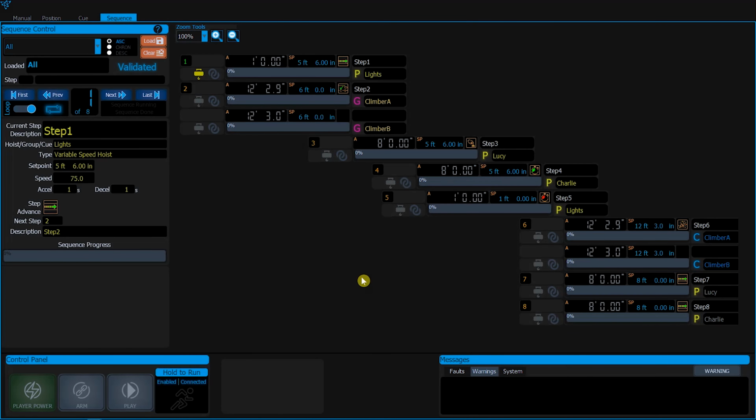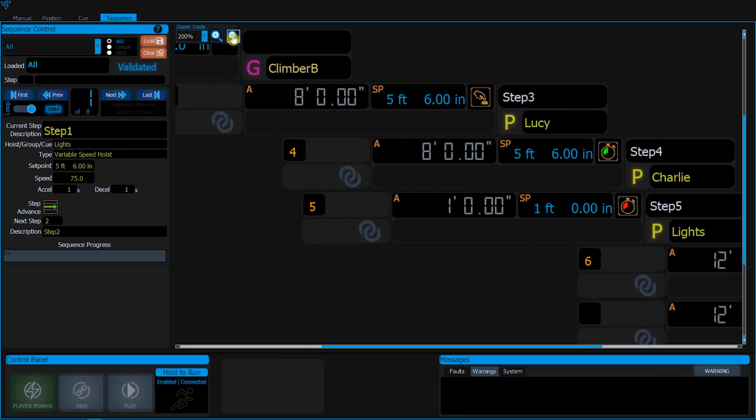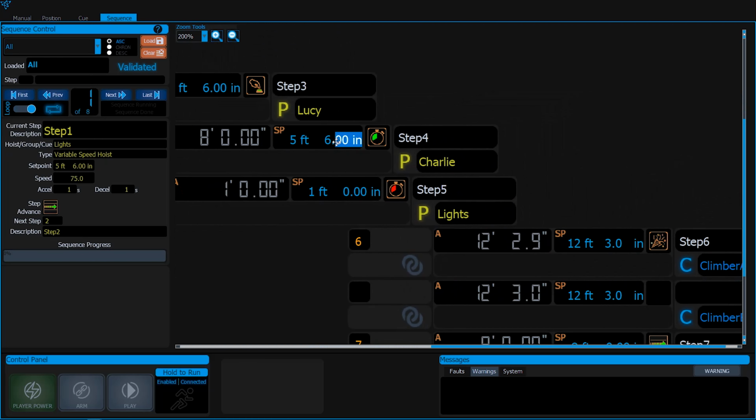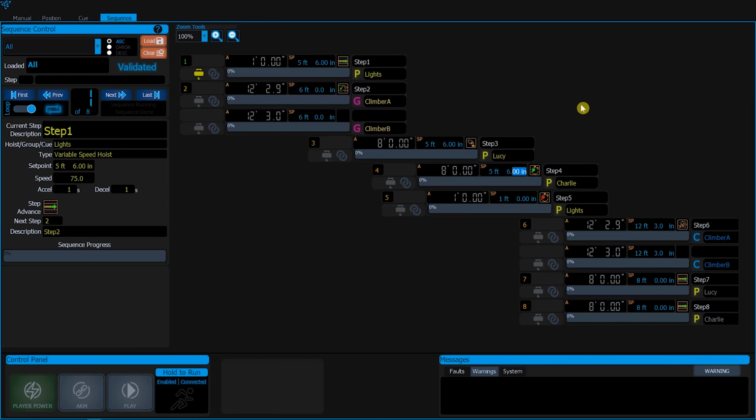The Sequence View progress bar can be adjusted for zoom and panning. To adjust zoom, use the zoom level drop-down or press the zoom in and out buttons. Panning is available at zoom levels above 100%, activated by a left mouse click in the View panel. Right-click on the screen to exit pan mode and reset the zoom level.